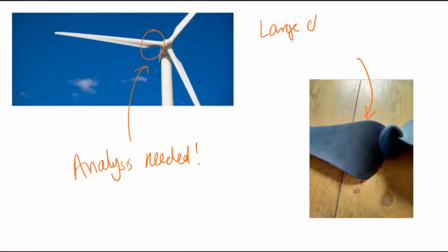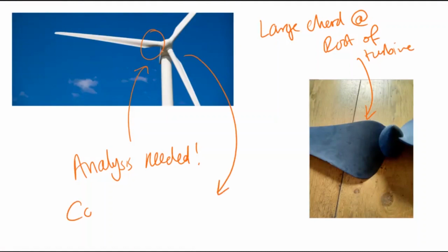The lack of root analysis also affected the max power TSR value, since we did not consider our root during the optimization. The large chord and twist of the root section meant that the blade would be optimal at a lower TSR than was estimated.